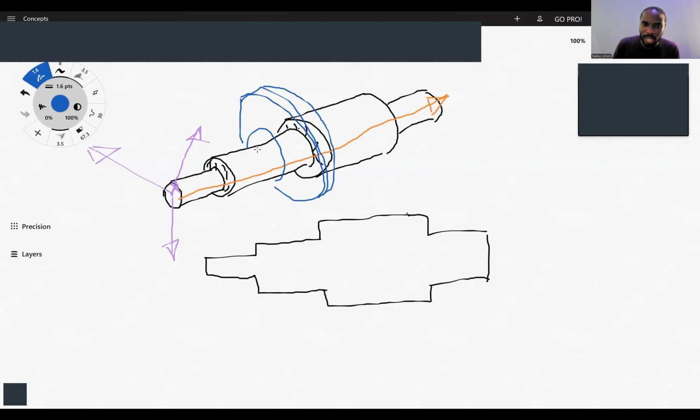Since this one is smaller, the gear will fit in as we are moving axially, and it will move until it gets to that point where the gear's inner diameter is lesser than this shaft's diameter. So it stops. So shoulders provide a very good way of locating your shaft elements axially.